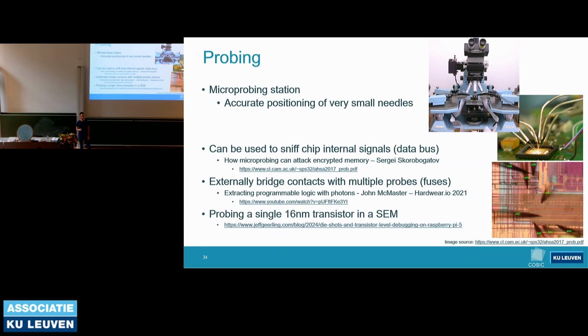When we move on, we go to probing attacks. So this is again an invasive attack because we open up the package and we put needles inside of the chip. This, of course, already becomes more advanced. You need more expensive equipment and so on. But there's quite a few things that people have done with these techniques. So, for example, some linear code extraction techniques where you would put a needle on the data bus, run the program, observe this one bit of the data bus in time, move the needle, repeat the process until you can get the entire data memory out.